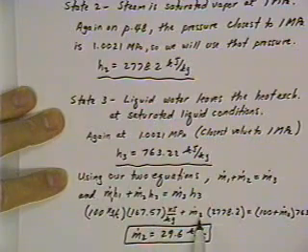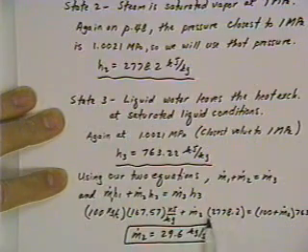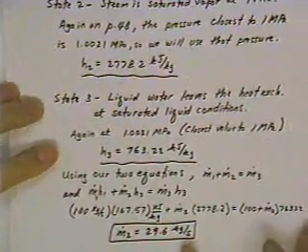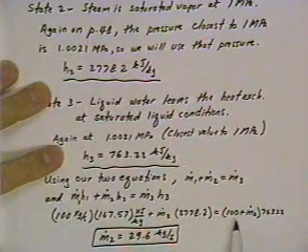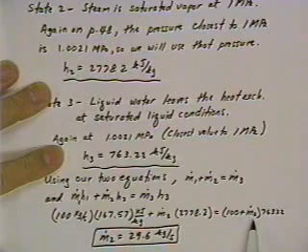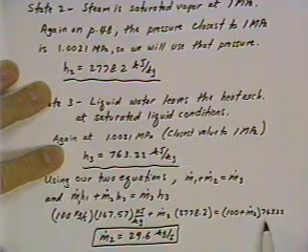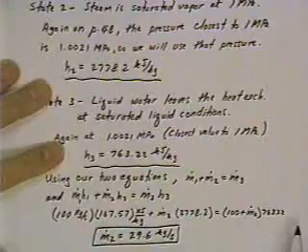That's really what we're after, because that's the mass of the steam. The mass of the steam enters with an enthalpy of 2778.2, and then that's equal to the leaving mass, which is our 100 entering m.1, plus m.2, which is unknown. But we know that we want to raise that up to an energy level or enthalpy level of 763.22.